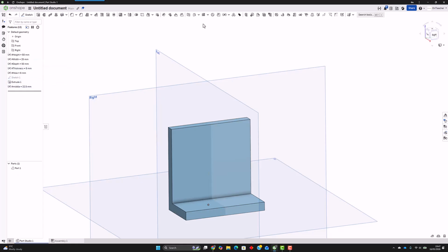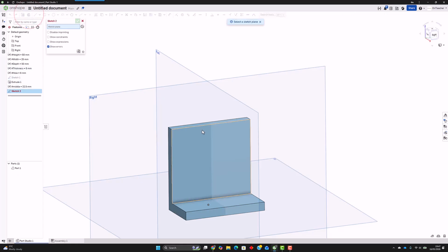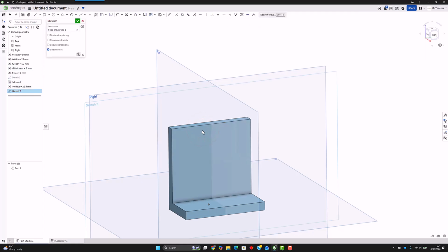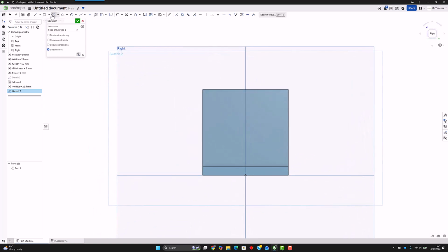So we've got middle. I'm going to click on sketch, click this front plane, press the N key, and I'll draw 2 circles. It won't let me type in again, so I've got to go to dimension. I'm going to dimension this one 12.5.